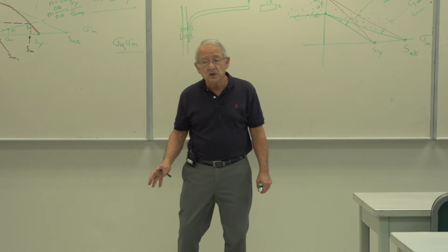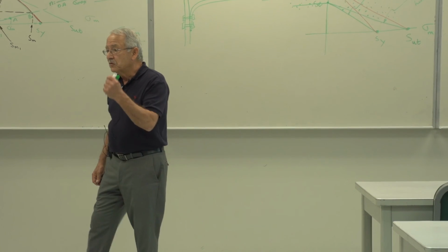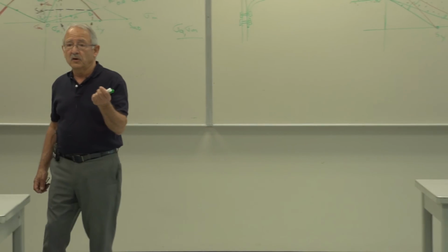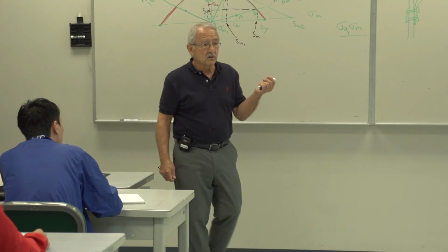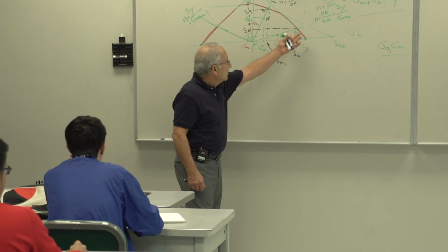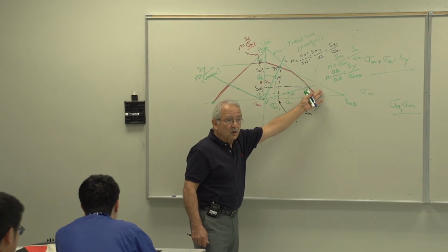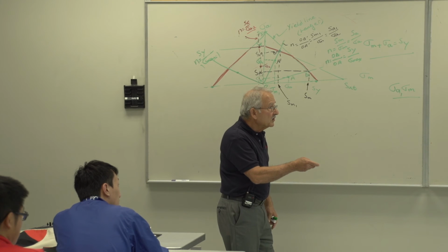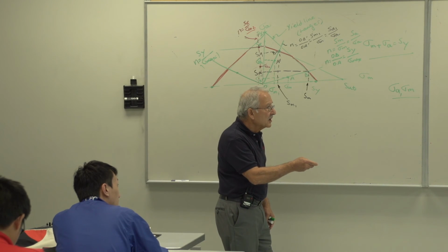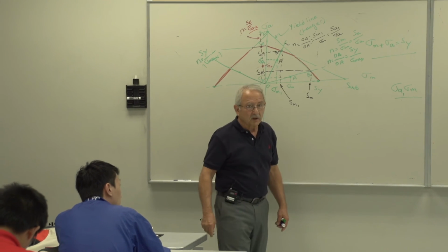Don't read the solution. And for those failure criteria that use linear failure methods, such as the Goodman or the Soderberg, use this method. Write the equation of the two lines and solve them together.